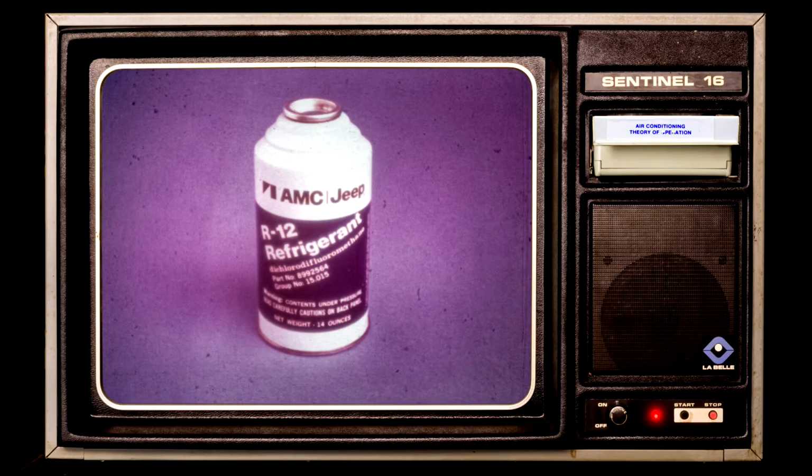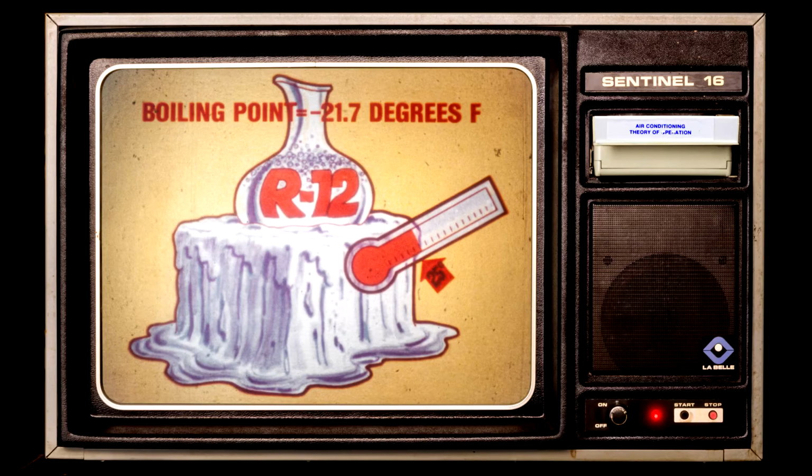Now, the key ingredient in automotive air conditioning systems is this refrigerant, which is known as R12. Although there are other types of refrigerants available, this is the only one used in automotive systems. Here, we've placed a glass container of R12 on a block of ice chilled to 25 degrees Fahrenheit. Because the boiling point of R12 is minus 21.7 degrees Fahrenheit, the R12 actually boils here.